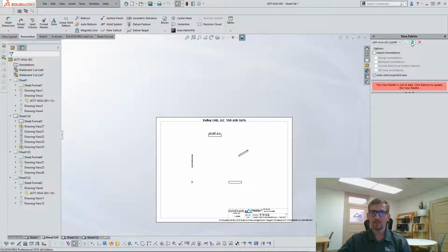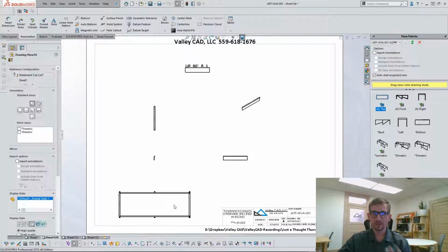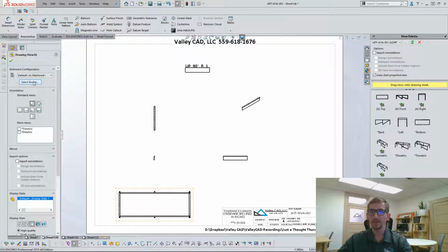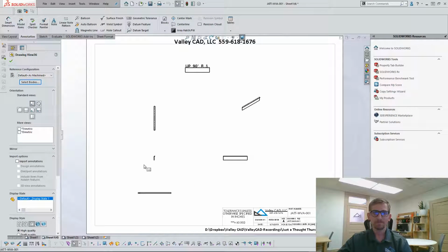And with that, I'll simply click refresh and I can import views from here as well. Okay, so simply coming over here, dropping that in. There's a primary view. Specify what body do I want out of this because it's a primary view, and I can say I want this one right here, and there we go. Okay, so do you import views that way?